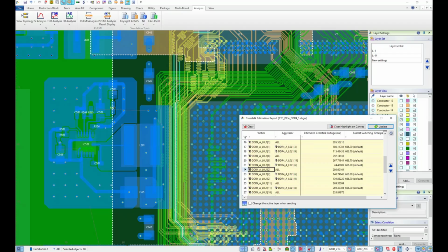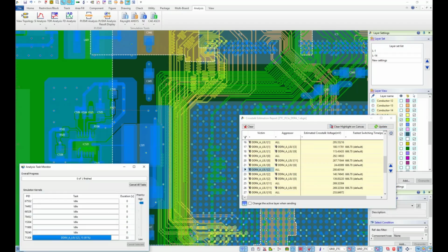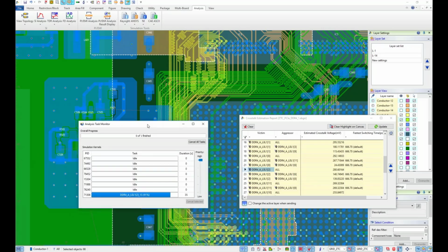So at the moment, it is conducting this crosstalk simulation, as we see here, on that selected core. And as soon as that crosstalk simulation is finished, which is more complex than an atomic transient for a single selected signal, so therefore it takes a little bit longer, but it's still a very fast transient simulation, I believe. So at the end of that crosstalk simulation, you will get the transient waveform of that crosstalk figure.